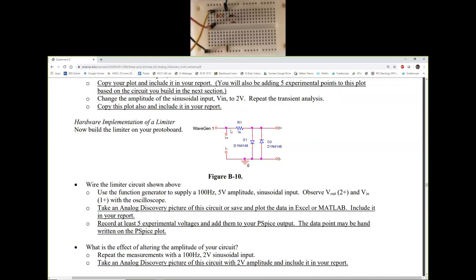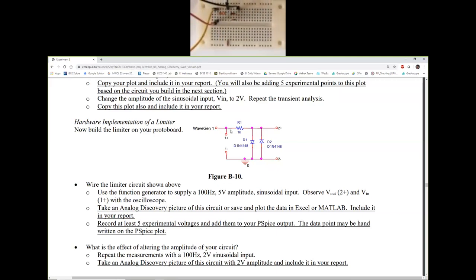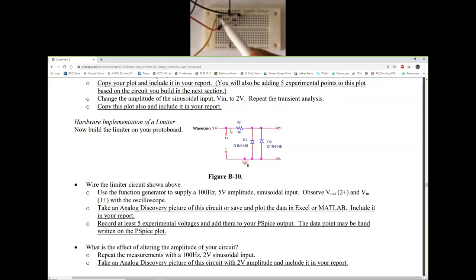So I've got the resistor, I've got those two, then I need 2 minus to go to ground. That's already connected externally, so that's fine. And I need the ground terminal right there. So I'm going to move the ground terminal to that row and zoom out a bit to give you the complete picture. So yellow, wave gen, same point, we have the resistor 1K, we are measuring using channel 1.